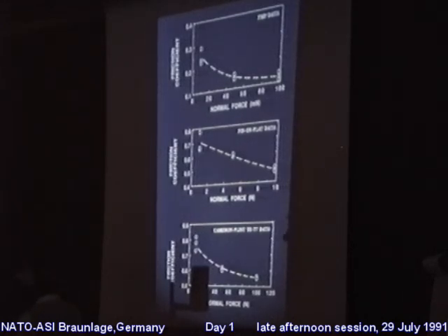Below it then, going from 1 newton to 10 newtons, the laboratory pin-on-flat machine, same specimen materials now. This almost looks linear. I don't know whether I'm going to claim that with three data per condition, whether that's linear or not. But we note that it goes from about 0.7 or 0.72, 0.73 on average down to about 0.5 here at the highest load condition. Now, that 10 Newton load happens to overlap with the low end of the Cameron Clint machine, a heavy duty machine.